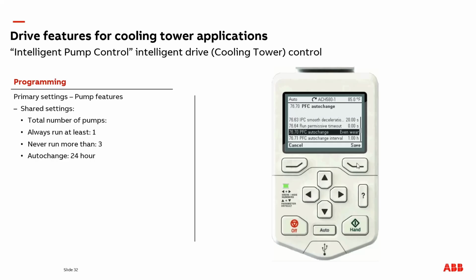and here's the auto change. So here we'll change this to timed function 2 that we have not set up yet. Here we could now set up time function 2 to enable once a week for a certain period of time. That will trigger each drive to switch who is the master. Here's our auto change imbalance settings and the priority.